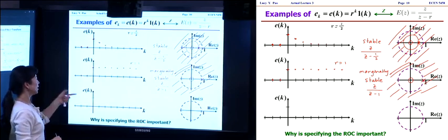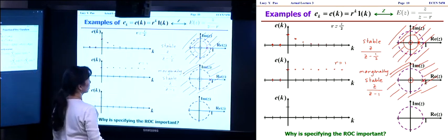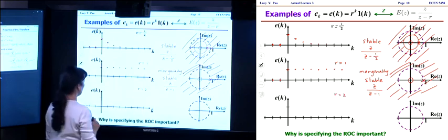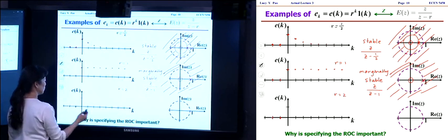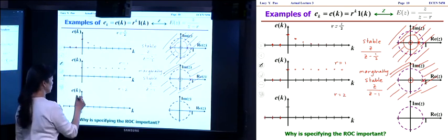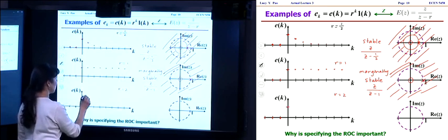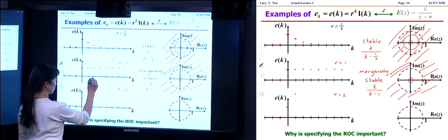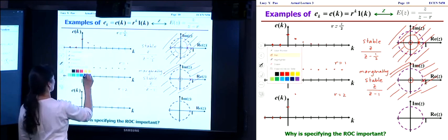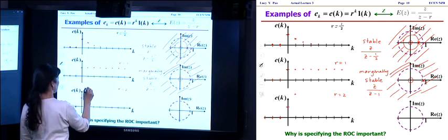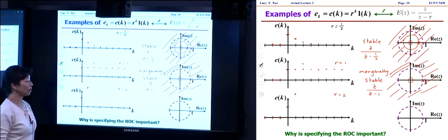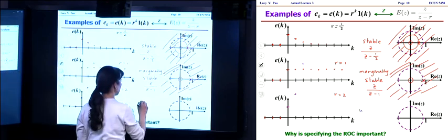It's not strictly stable; it's what we might call marginally stable. Now let's look at some R greater than 1. Let's look at R equal to 2. Again, it's 0 for negative k, since it's a causal signal, and then it'll be 1, then 2, then 4, so we have 1, 2, 4, 8. You can see it will quickly diverge, so it's unstable.